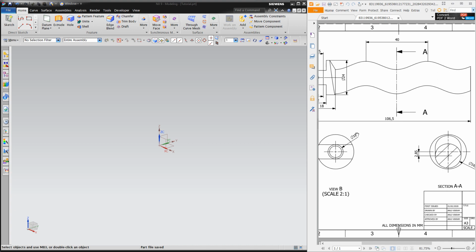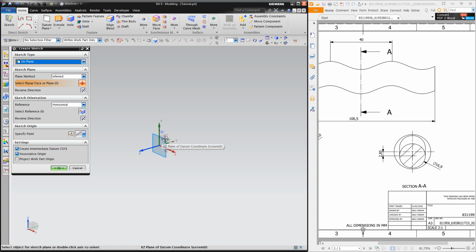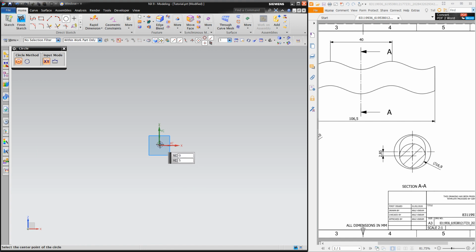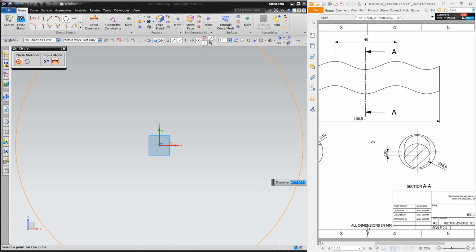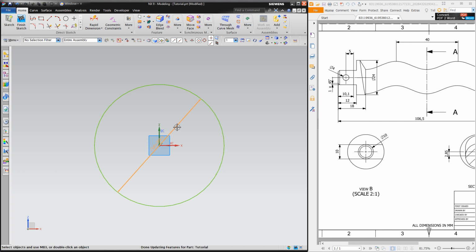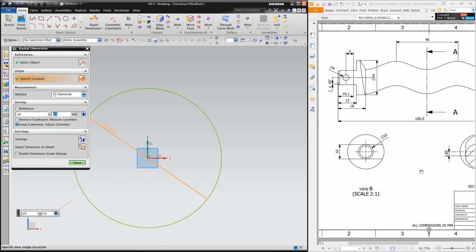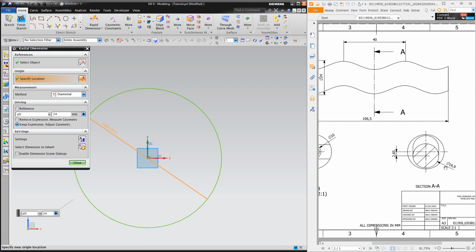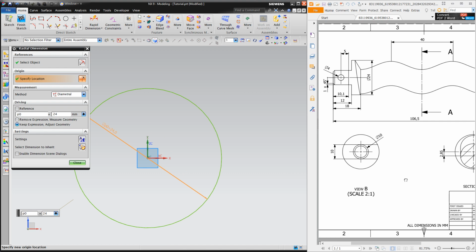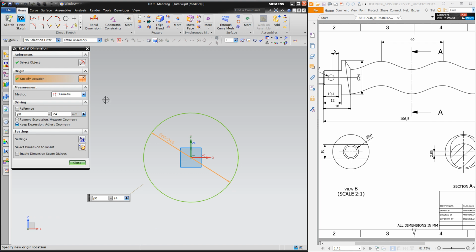So I started from this 2D. See how I choose this plane in the sketch environment. I make the circle, this size is 24. This is a 24 dia circle. Okay, this is the round bar, dia is 16.9. So we create it.